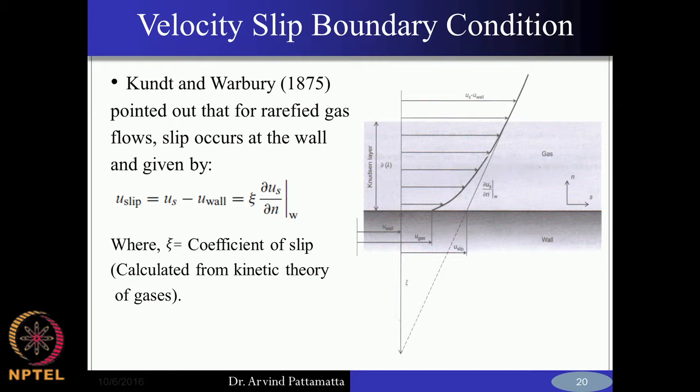So, therefore, directly the apparent origin will be directly from the wall. Now for higher Knudsen numbers, this origin or virtual origin seems to shift into the wall because of the slip effects, and therefore the slip length zeta seems to be a finite value, and this increases with your Knudsen number. So, how do we incorporate the slip effects?